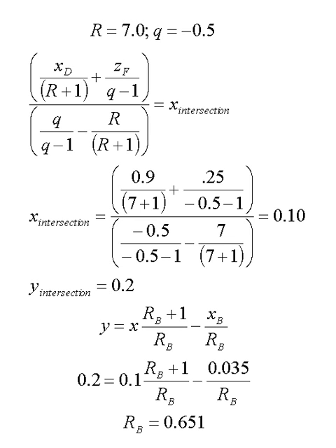Now that we know that point of intersection, we can substitute those into our equation for our lower operating line. And since X and Y are known, we can solve for the value of the boil-up ratio, R sub B, and in this case that would equal 0.651, and we'll use this value later on in the presentation.